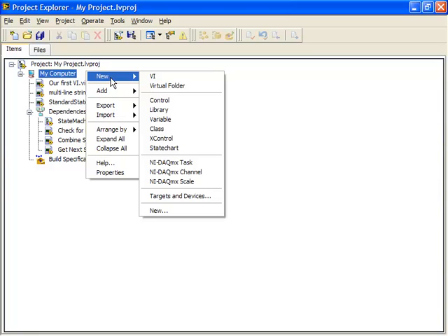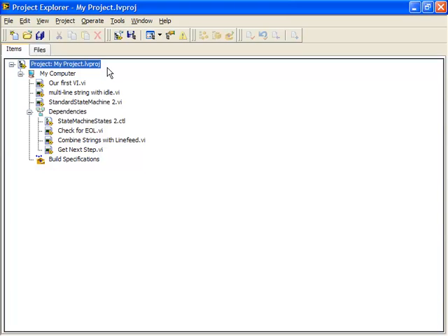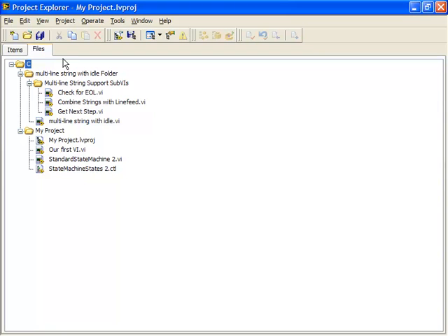Other developers choose to develop without using the Project Explorer screen and add files to it later. Either way, it's important to structure and plan your project carefully, in particular in the way that you store the files on the hard drive. As we saw here, we have two important VIs within our project residing in completely separate locations. And as mentioned, it would be very easy to back up or make a copy of this entire project and miss one or the other of these individual locations.